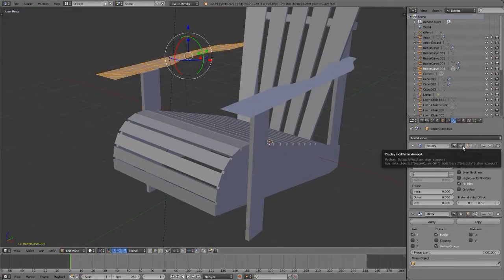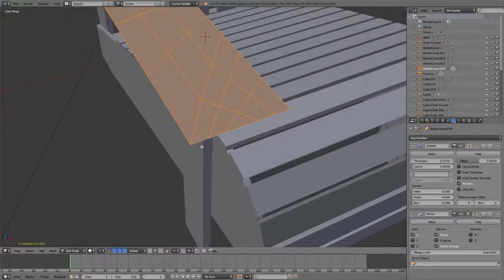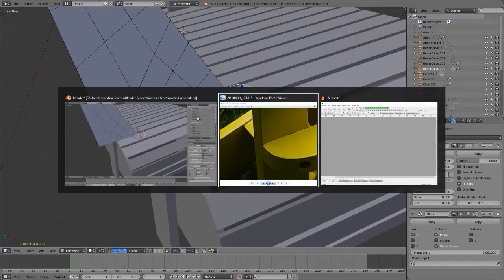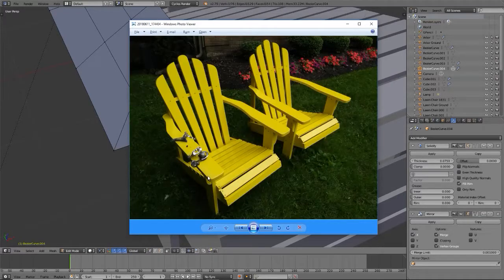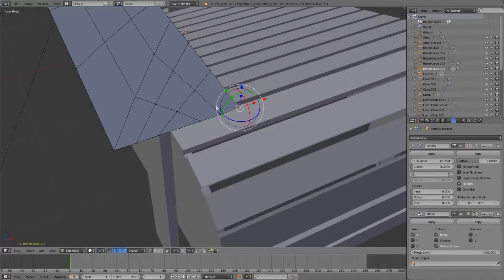Go into these arms and let's relax the vertex. I was worried about this. Okay, Control Tab V. These vertices need to smooth out. They need to bevel. Speaking of, this right here, they need to do that. This one's going to be easy. Shift Control B, you can bevel it and then smooth it out.